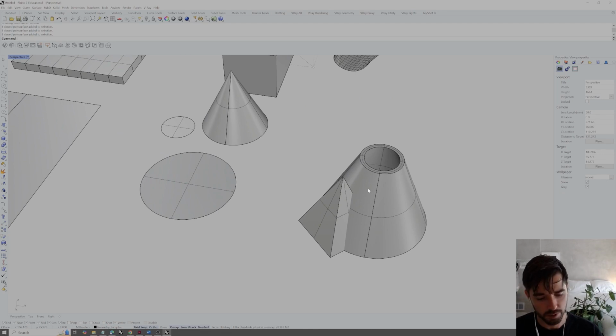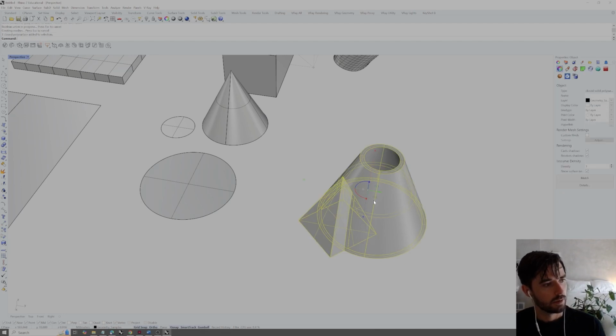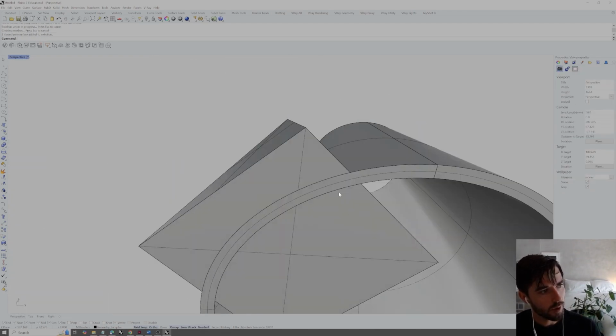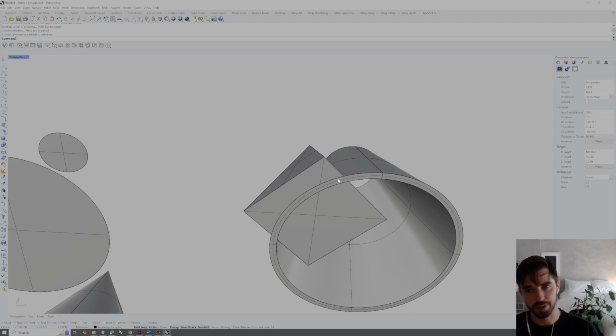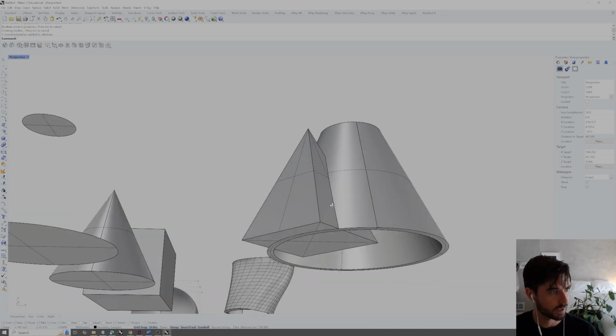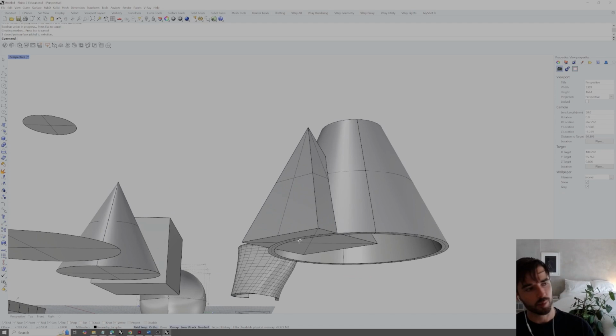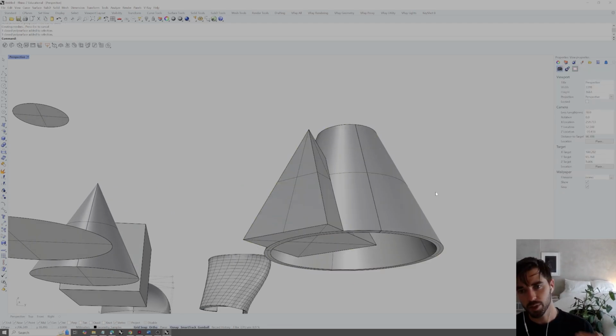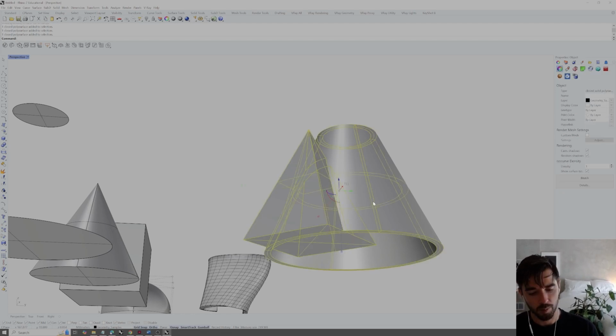So let's say we wanted to add these together again, so Boolean union. We now have that kind of remnant from both of these being added together, so we see both surfaces still, but it's actually in an even plane. So if we want to clean that up, because Boolean operations, since they're doing these kind of combinations, quickly make your file messy or your geometry messy, what we want to do is merge those surfaces to make them a flat plane again, combine them into one clean plane. So we can do this by typing merge all coplanar faces.